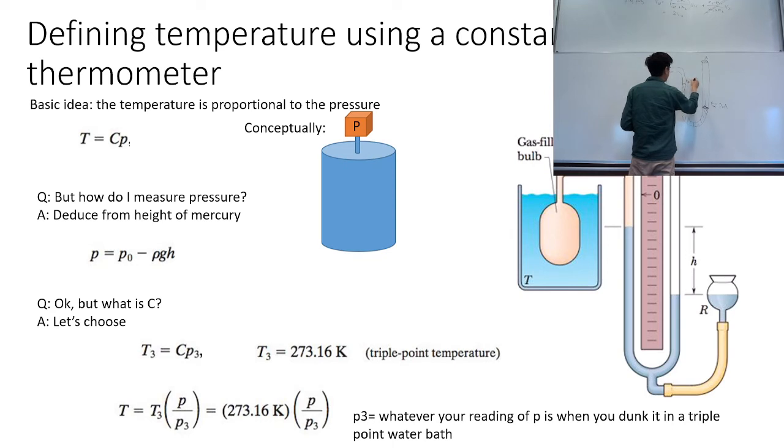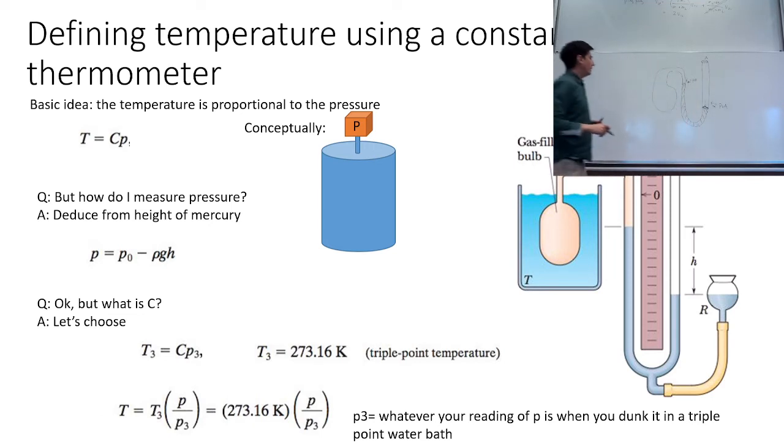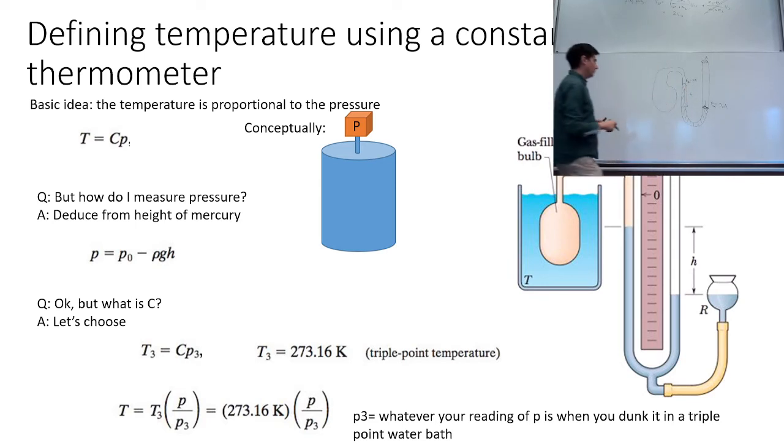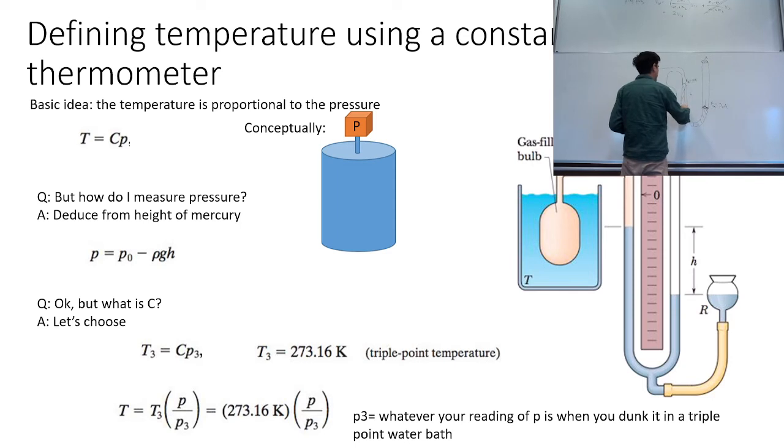So we've got some different pressure, A. And there's also the weight of the mercury on this side. And this force that's acting over here would be equal to the force of the gas plus this weight of the mercury.